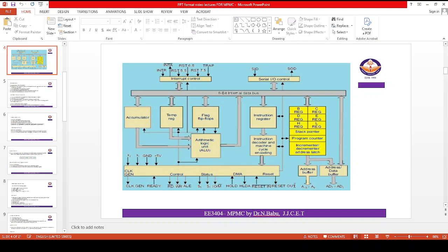The same thing happens with the D and E registers. Both are 8-bit registers. If we combine the D and E registers, finally we get the DE register pair. We can transfer 16-bit data through the DE register pair. Okay, do you understand now? Next, the HL register. H is one of the 8-bit registers and L is another 8-bit register. If we want service with 16-bit data, we can combine both H and L registers. Finally, we get the HL register pair. The HL register pair's other name is memory pointer. It is used to hold 16-bit data.